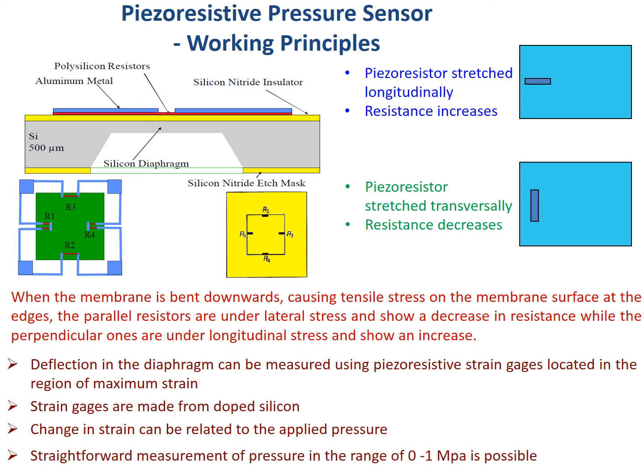Right? So what we understand is that depending on the orientations of the piezoresistors, the locations or the placement, we have to put them in such a way that when the pressure is applied, if we use 4 strain gauges in this full bridge configuration, then 2 piezoresistors will increase their resistance, whereas the other 2 will decrease, so that we can connect them to the Wheatstone bridge in full bridge configuration and we will get a larger Vout. Fine? Okay.